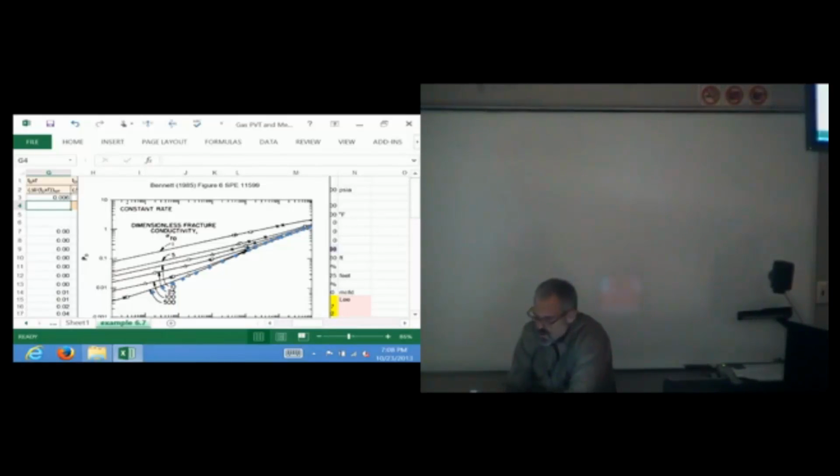You kind of have to do a little bit more work when you're looking at dimensionless fracture conductivity less than infinite. And basically, when it's about 500, it behaves as infinite. And really, I'm not trying to match these first few data points because I'm going to run off my line up here, and I'm bounded up here by this line. First thing we do is really put it on that type curve and see if we have finite or infinite conductivity; I'm going to answer that question even more fully.